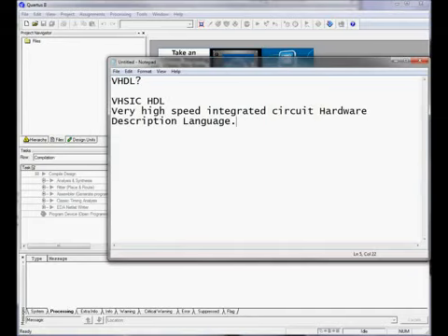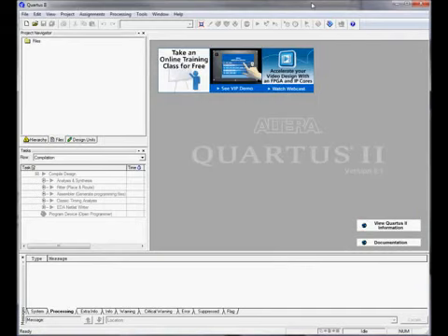And what is that chip? Well, you'll see it in the lab, and it's what this thing in the background is here. This is Quartus 2. And Quartus 2 allows us to compile designs for the Altera family of FPGAs, or field programmable gate array chips. And these chips are customizable via software download, so that you can demo or model pretty much anything that you want to on them within reason. So for instance, if I have an FPGA chip, I could put a simple stopwatch on it, or I could put an MP3 player on it. It all comes down to what I've designed for it and what I can use it for. In your case, you'll be building a processor on it that'll do some simple processes like addition, subtraction, XOR, and so forth. So let's take a look at the Quartus 2 IDE right here.